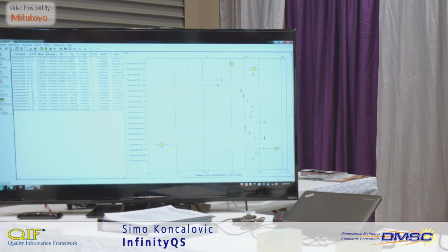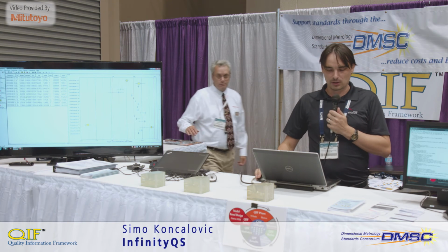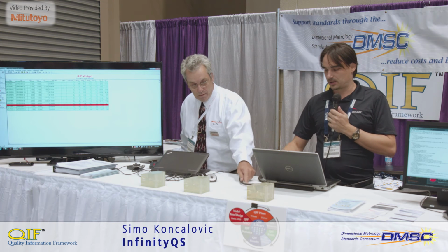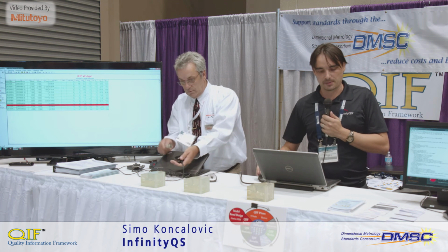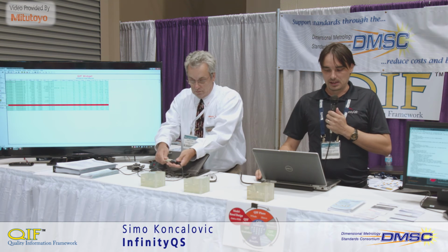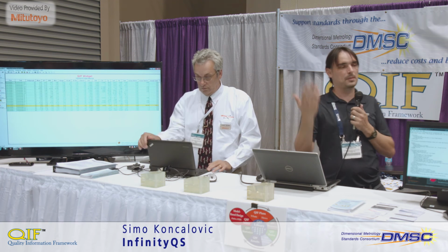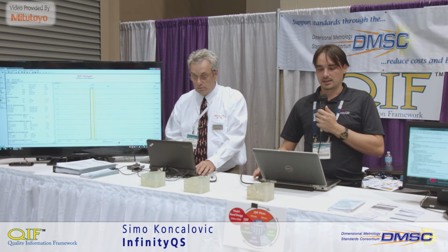For example, here, characteristic 71 is a little bit below spec limit. This is actually one of the hole diameters. That's a bit below spec, but that's okay. We can also look at some of this information in more of a summary type of analysis, see if there were any alarms and when they occurred, and also a capability summary report to understand where our capability is at.